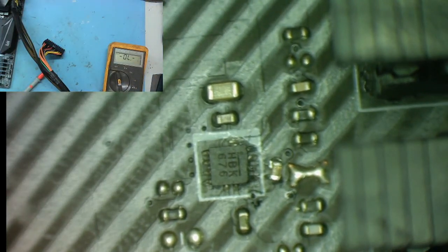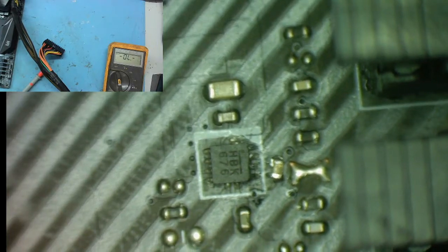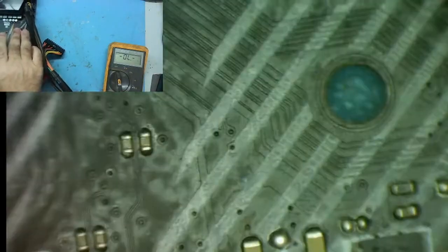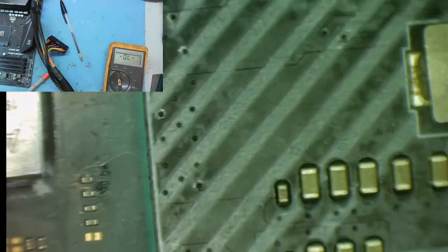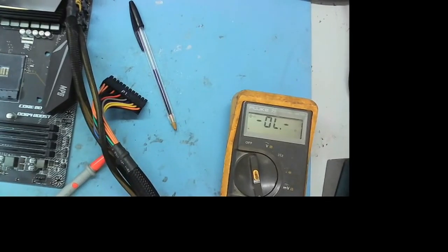HBK 676. Before we do that, I just want to chat to you guys about what we've just done, about how we found this fault. We found this fault because we had another board of the same chipset, and we measured some voltages which we thought weren't right, and then we compared it with the other board, and we could see that we were exactly correct, that those voltages were wrong. But would we have been able to find that fault if we didn't have a board to compare it with? Would we still be able to determine that we had a fault there?